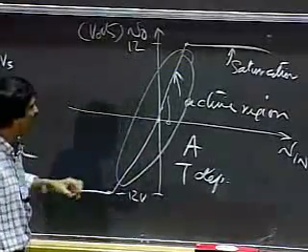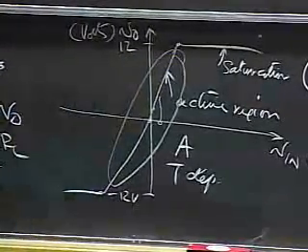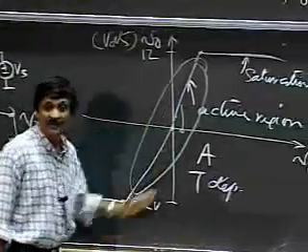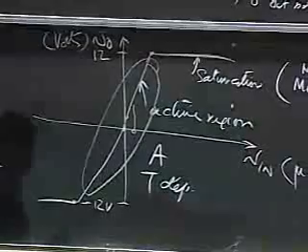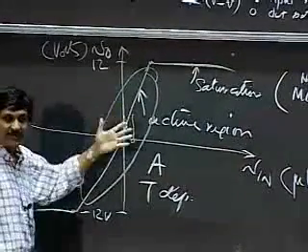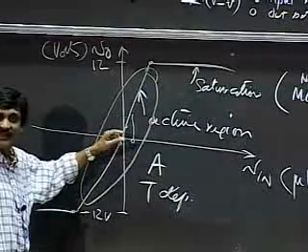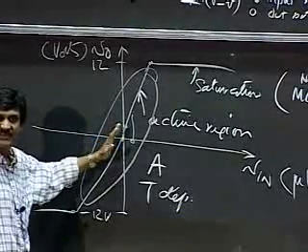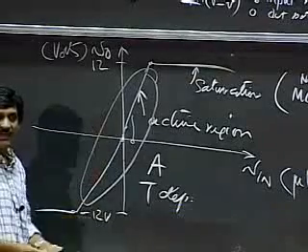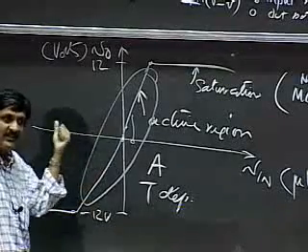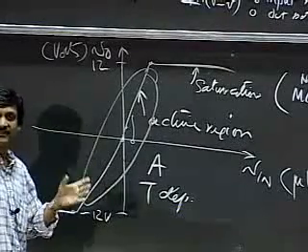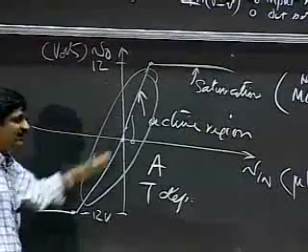So let me show you an example. I'm going to show you this curve for this amplifier, applying an input and plotting the output. Then I'm going to use a heat gun to heat the op-amp, and you're going to see this vary all over the map. Some of you may remember from last week a similar situation, where the gm for the MOSFETs you were given was also dependent on temperature and stuff like that. It's a very common occurrence, and that's certainly the case for the MOSFET.